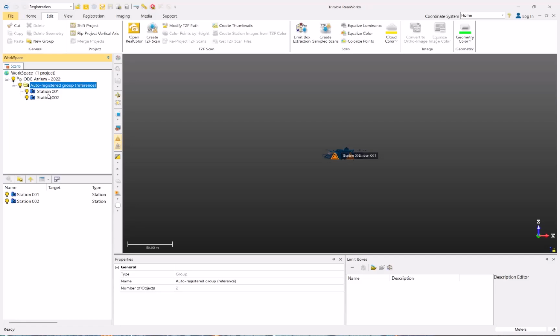2 stations, station 1, station 2, and those need to be stitched together, similar to when you are stitching panoramic photos together. It'll try to find common points, common areas, and match them as good as it can, and actually gets it pretty well matched, as long as it's indoors. Outdoors, where you don't have as many similar planes that it can find automatically, it gets a little harder, and you may actually have to do some manual correction.